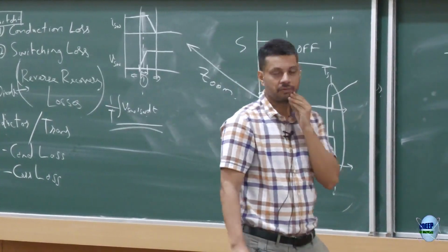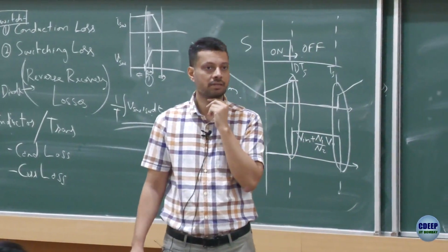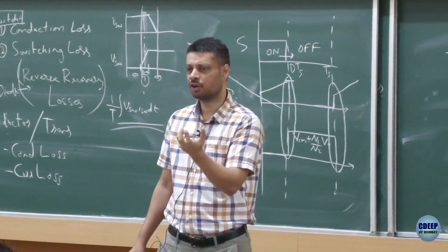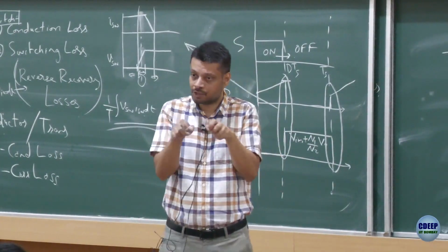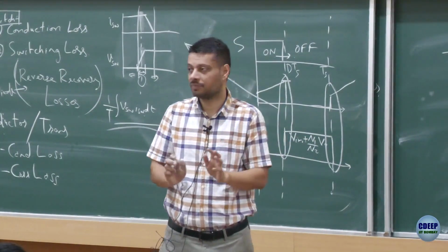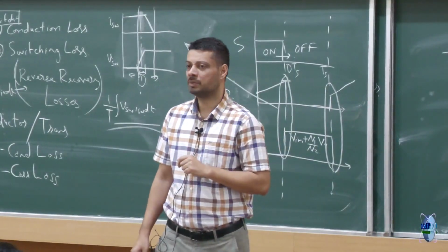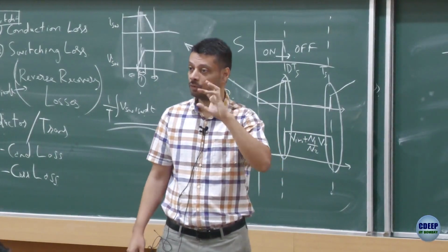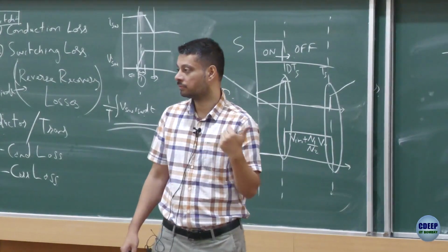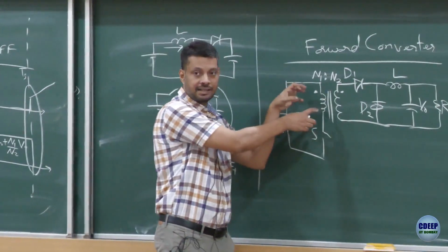Unlike flyback, which is actually really good, you would find a lot of applications around you. Any electronic board you open may have a small flyback sitting somewhere there. Forward is not as common a circuit, but it's very important, because this changes the whole principle of operation from the flyback, where you are using the magnetizing inductance itself.